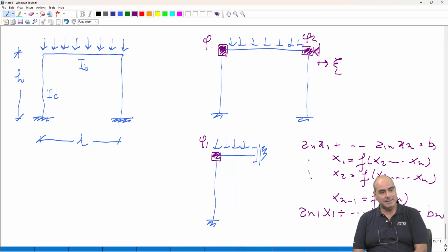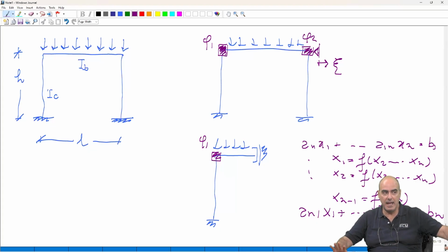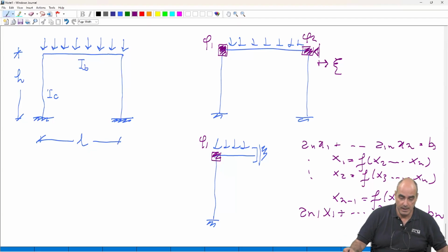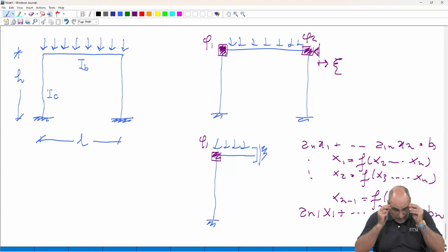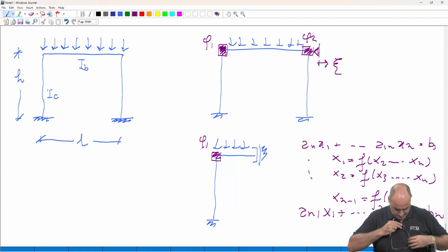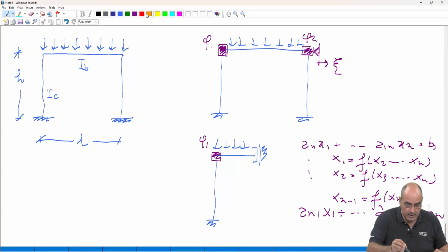But in buckling analysis, we cannot rely upon symmetry. And I can show this without solving any equation. Just look at this structure here. If we allow the symmetry, and then force it, the way in which our structure can buckle, well, this element can rotate a little bit.